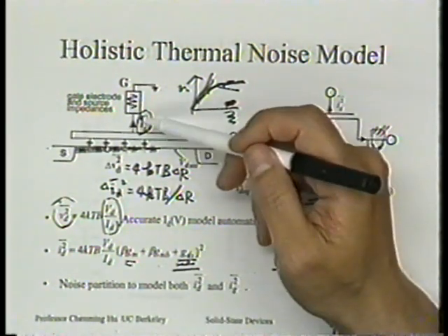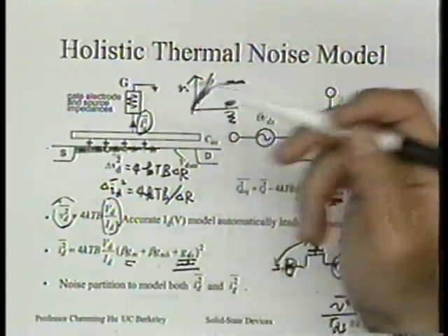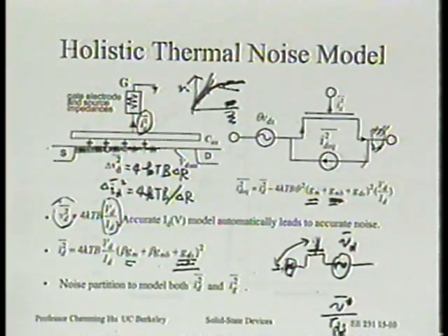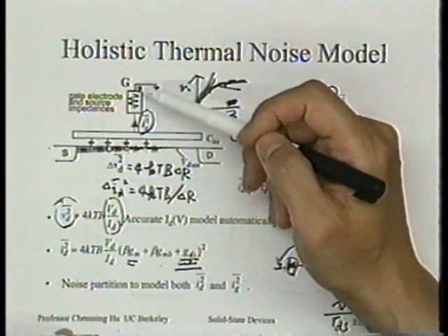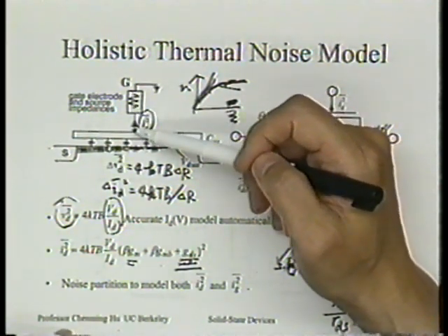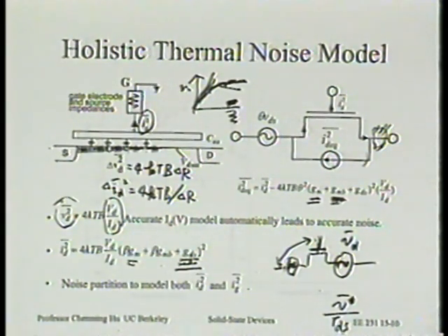Now, if there was no resistance in the gate, then there's no problem. This gate current simply flows into the ground, does nothing. But if there's any impedance in the gate circuit, this current is going to generate a voltage at the gate. IR drop, so-called.